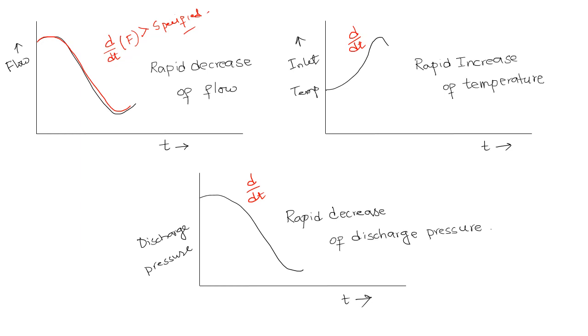So as you have understood, these signals are captured by the sensors, the input devices. For example, for the flow, there is a DP transmitter that provides the signal to the anti-surge control system or anti-surge detection system. Now, the accuracy, repeatability and response time of this DP transmitter are of utmost importance.